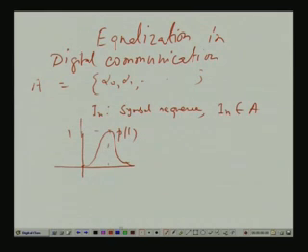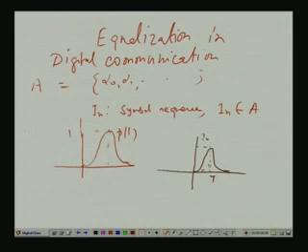Now, suppose with this pulse you multiply the pulse by I(0), so height will be I(0). You trigger it here and measure it at the receiver at this point of time, say capital T. But since you are transmitting fast, you will not wait up to time capital T; you might trigger the next pulse at tau and multiply the pulse by I(1), at minus tau you trigger another pulse, I(-1), and so on and so forth.